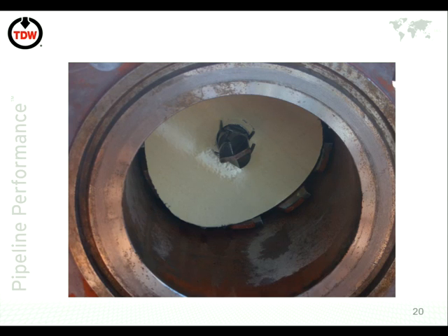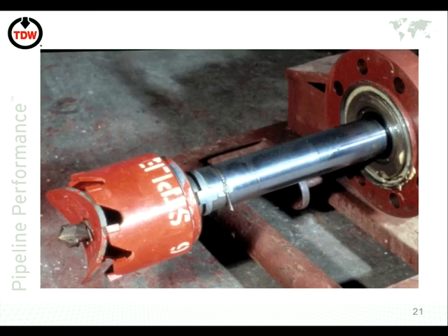And there you can see the U-wires, just on the edge, and this is the piece of pipe which has been removed. So we've drilled that hole for that diameter, and then we've withdrawn that out of the pipeline. So that pipeline would now have been left with a hole to that diameter in there. But more importantly, there will be no piece of pipe lying in the pipe which would restrict any pigging operation, for instance.